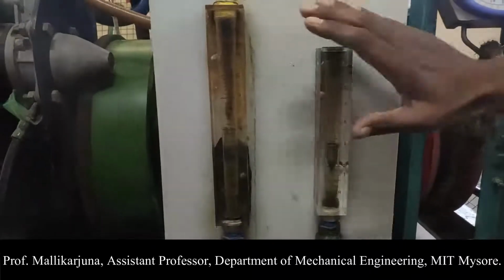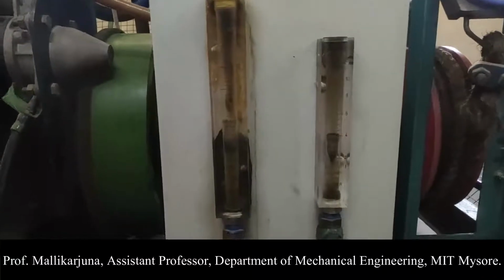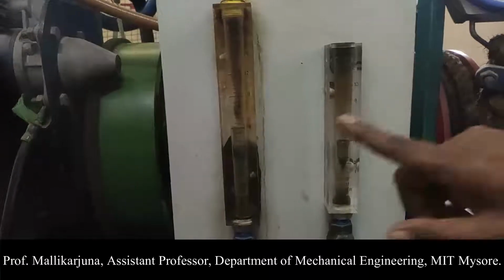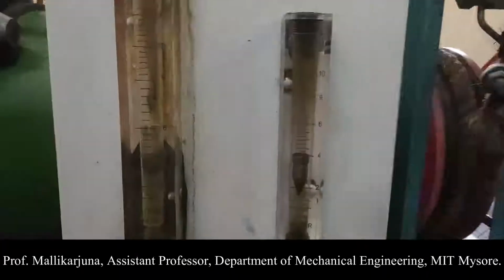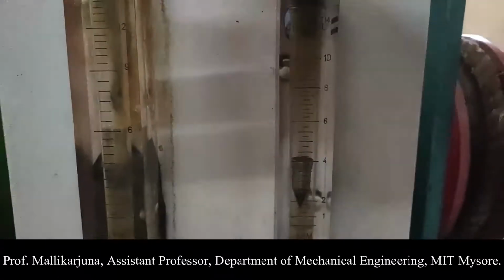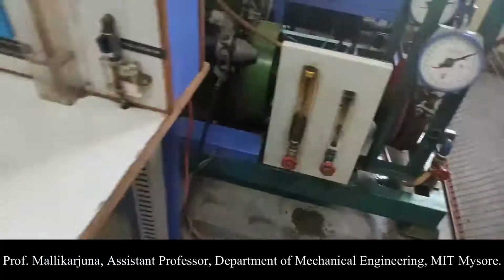The calorimeter water supply is required in order to look onto the amount of energy which is carried by the exhaust gas in the form of heat. Towards the engine we have 6 liters per minute of water, and towards the calorimeter we have 4 liters per minute of water. So these two methods are used in order to check the water supply.